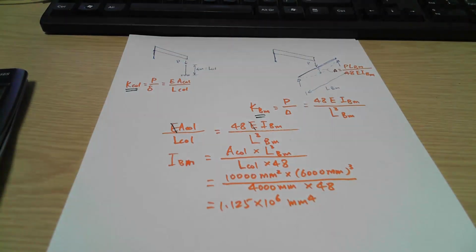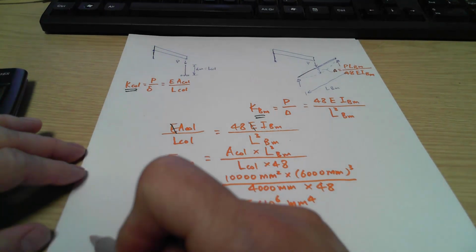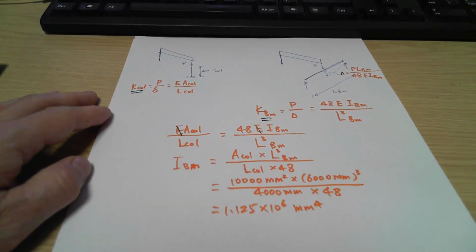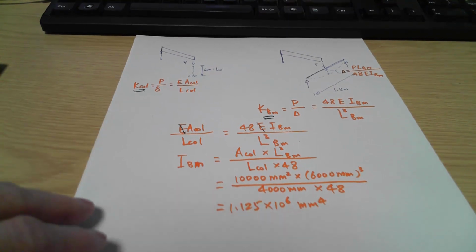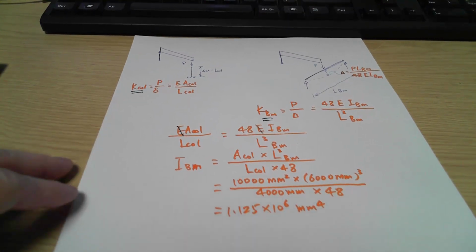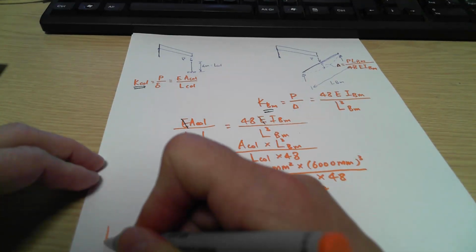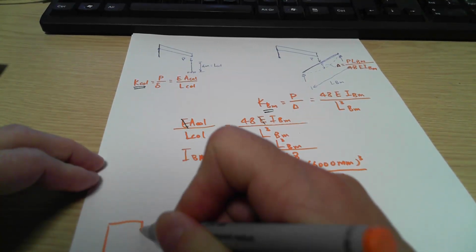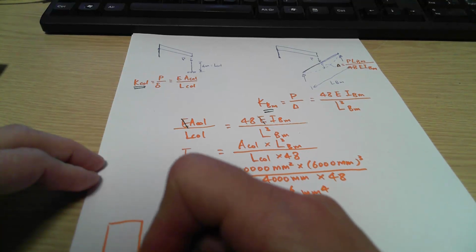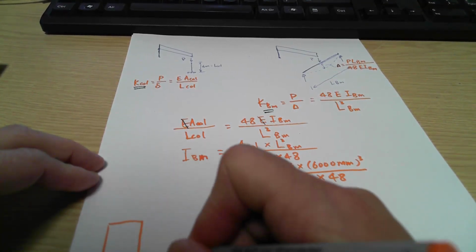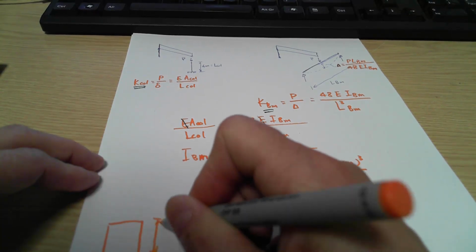The second moment of area of the structure can be different if you use a different cross section. The simplest one, I think, is still the rectangular one. If we use a rectangular beam, you have two parameters to decide: the breadth of the beam and the height of the beam.